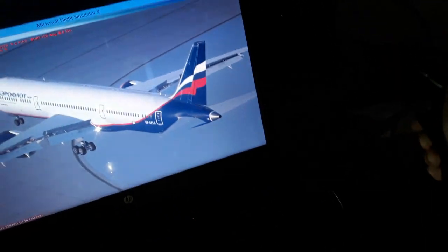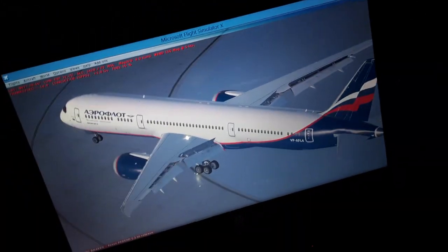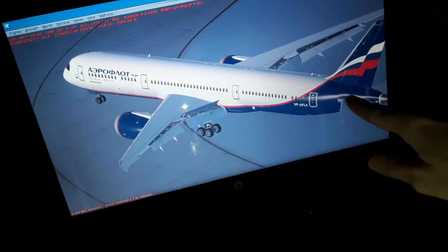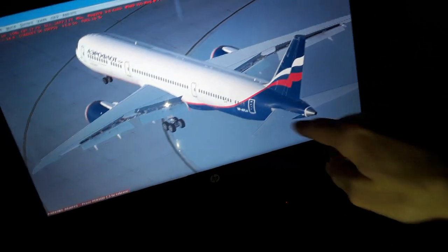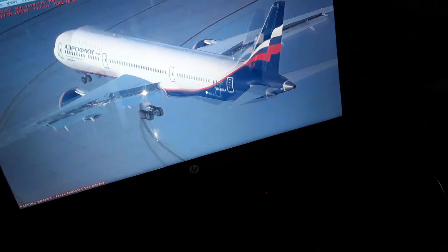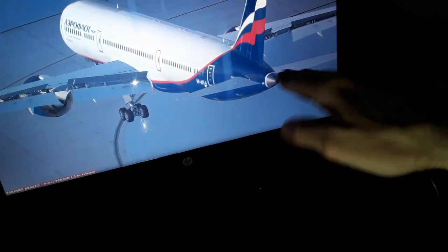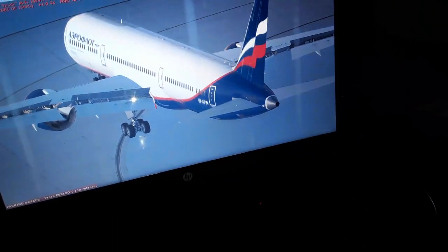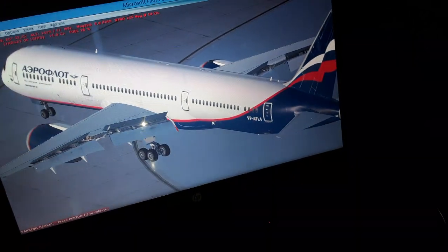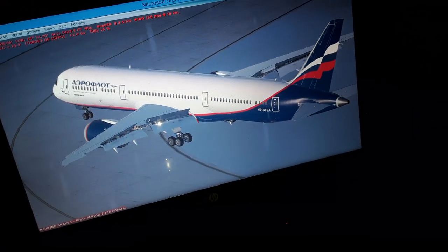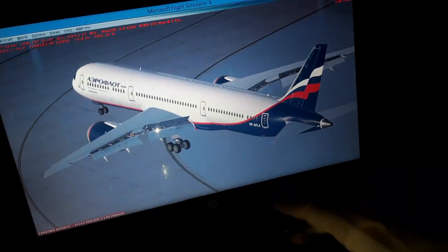So you can climb and turn. You can see also we have, as I told you, the longitudinal axis from nose to tail. We can pitch trim. I will show you later the pitch trim stabilizer, the horizontal stabilizer. We can pitch trim the tail of the aircraft up and down, or the elevator as we fly, to make the aircraft more balanced and stable in flight.